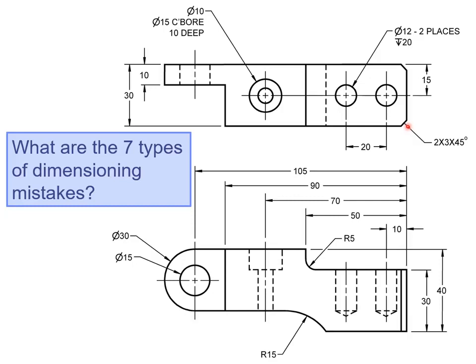From an imaginary intersection point to this point, it's 3 units with an angle of 45 degrees. Again, the 2x tells us that there are 2 chamfers. Another thing is we want the leader to be floating upward. So we want the text to be floating upward and the arrowhead pointing downward. Even though this is correct placement, it still looks better if it's floating and pointing downward.